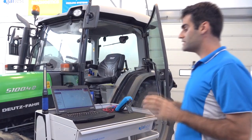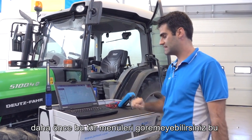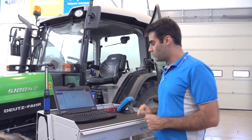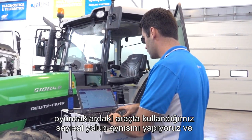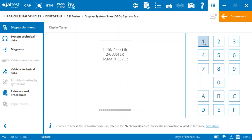For those who already know how to use Jaltest, you may not have seen this type of menu before. It's an alphanumeric menu. As I told you, we do exactly the same numeric path we have in the tool from Deutz, and we need to follow the numbers with the pad. So if I want to connect, for instance, to the rear lift, which is number 1, I need to click number 1.